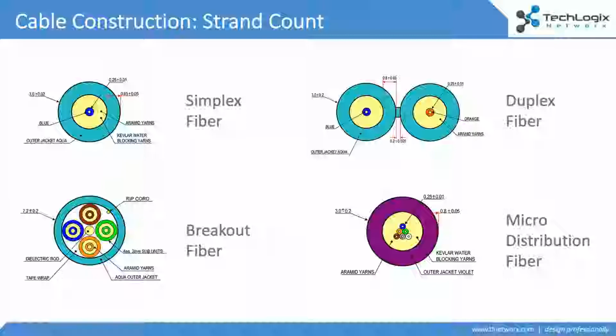There are different types of fiber when you're designing a system that you really can optimize to create an ideal infrastructure, an ideal installation, right? Simplex is the most basic fiber. And a lot of people tend to talk about the different strands inside of fiber as conductors. You're really not conducting anything. That's one of the things about fiber optics. There is no power transmission, right? Now, the good news is that makes fiber cabling immune to electrical noise, electromagnetic noise, RF interference. It doesn't worry about things like lightning strikes or static electricity.